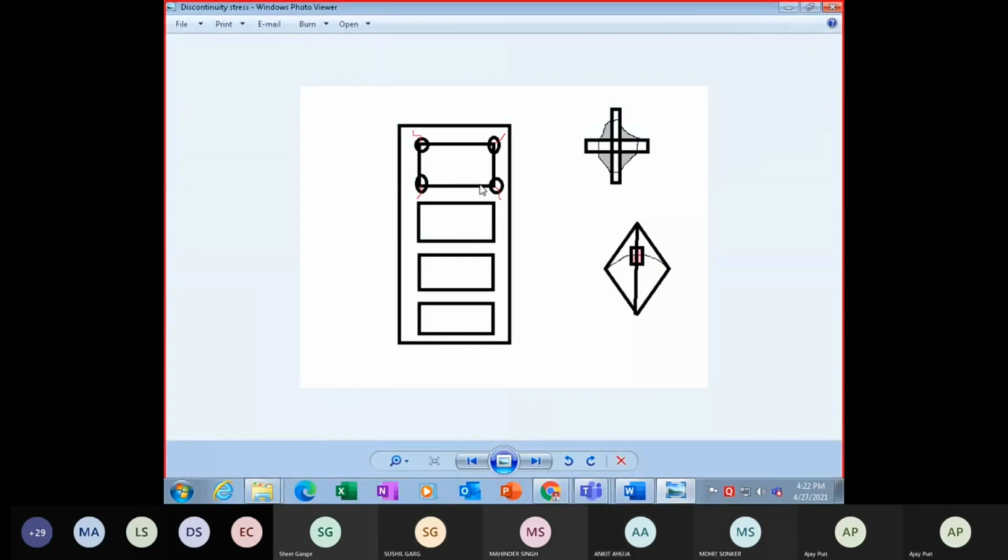Now because of your large openings in the hatches, the corners are subjected to discontinuity stress. So you connect a gusset plate like this on the hatch member, below these joints. It is like your kite. You have those sticks here, you connect a piece of paper here. The paper is acting like a gusset plate and supporting the members. So similarly, the gusset plate is supporting the members and spreading the stresses over the area. Otherwise, the corners would break or fractures would come up here. So this is the spreading of stresses done by the gusset plate.